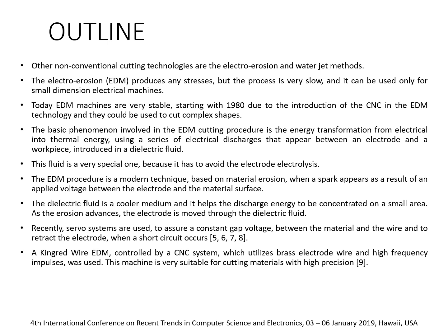Recently, servo systems are used to assure a constant gap voltage between the material and the wire and to retract the electrode when a short circuit occurs. A Kindred wire EDM controlled by a CNC system, which utilized brass electrode wire and high-frequency impulses, was used in the paper. This machine is very suitable for cutting materials with high precision.